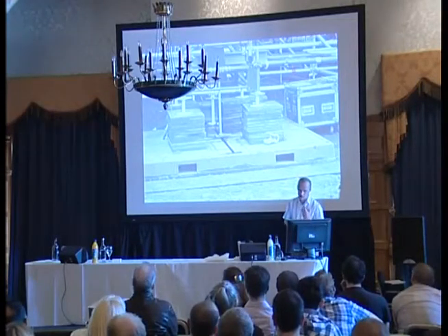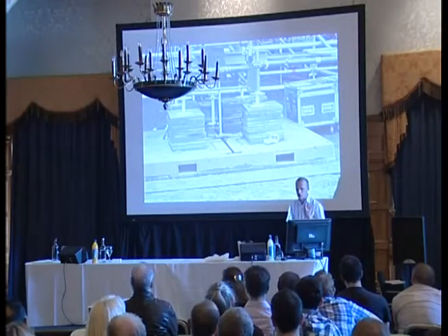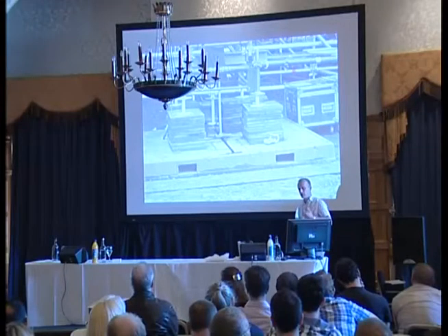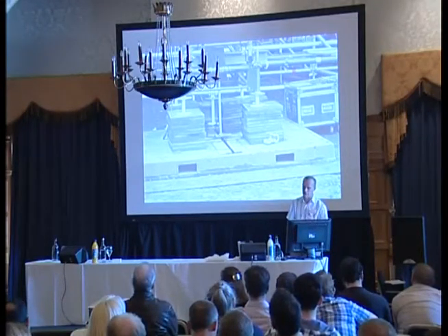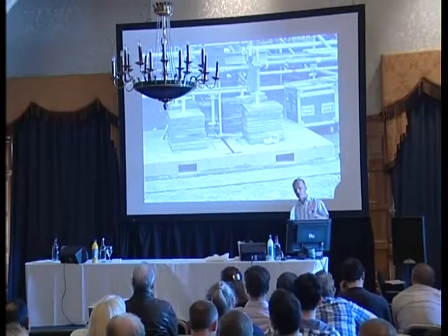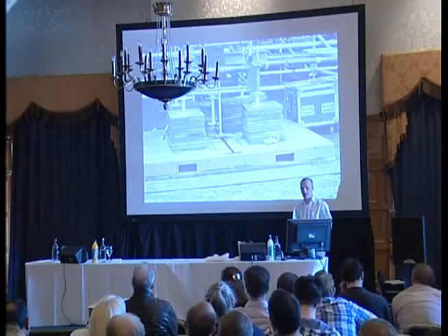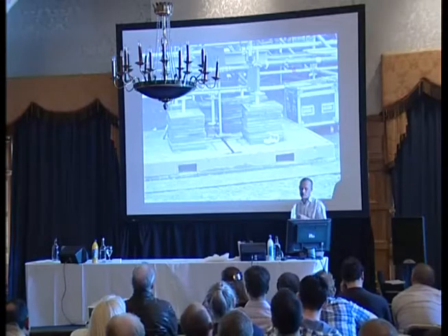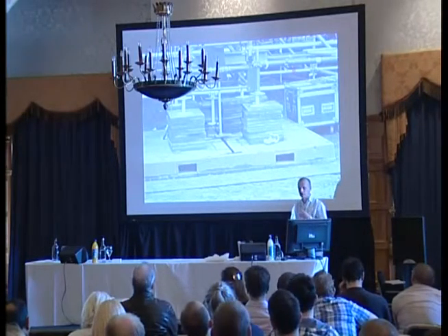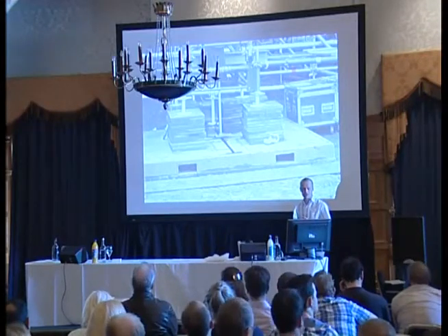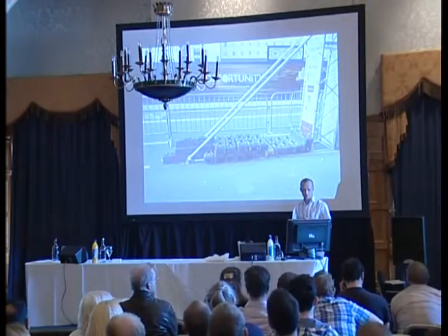Again, I am not saying what's right or wrong. We need to ask the questions though when we're out on site. Why have you done it like that? Is that safe? What are you going to do about managing it? How are you going to make sure that somebody hasn't punched a hole and taken all the water out of that ballast? So that might take a regime of inspection.